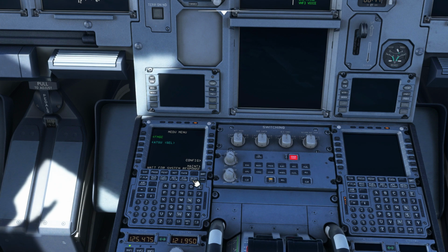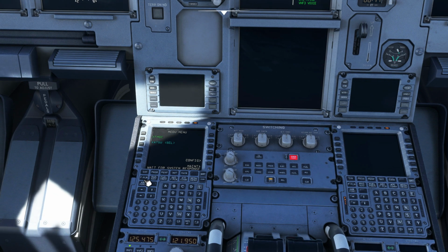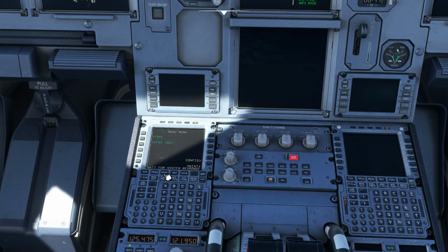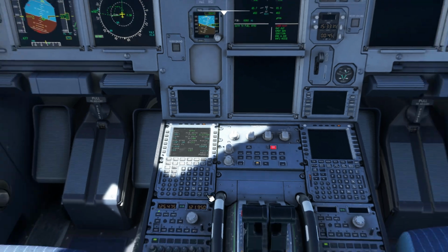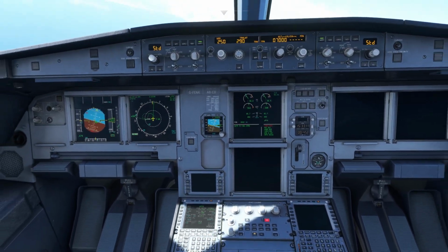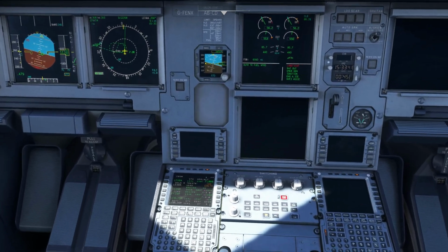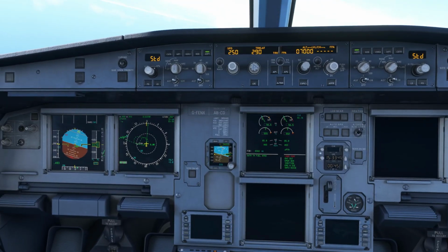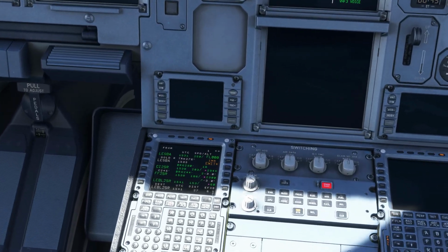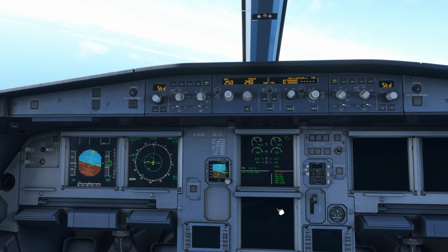Secondly, we are in alternate law, and will enter direct law when the gear is down, so you will have to trim manually, and then we have no reverse and you will need to brake manually. I agree. Also MSA is 4,300 to the north, although the approach and go around keeps us over water. As I am flying raw data, please call localizer alive and glide slope alive when you see it. The weather is good, Cat 1 with about a 5-knot crosswind.